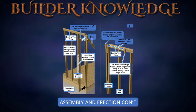Now it's time to plumb and align the wall. Plumb outside corners first and securely brace them for safety. Align and straighten the wall tops after all the corners are plumbed, but before nailing floor or ceiling joists to the tops of the walls. Fasten a temporary brace to a wall stud at each checkpoint. Do not remove the temporary braces until the framing and sheathing for the entire building is complete.